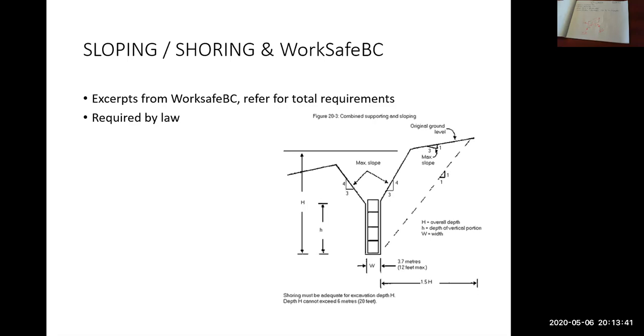So typically compacted road base and compacted road subbase is a Proctor value of about 2.3 tons per cubic meter. So that's 2,300 kilograms per cubic meter. So that's why I typically suggest either 2.2 or 2.3 as your conversion factor. So that's compacted in place volumes converted to tons.